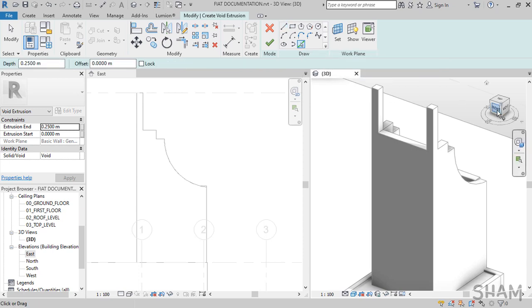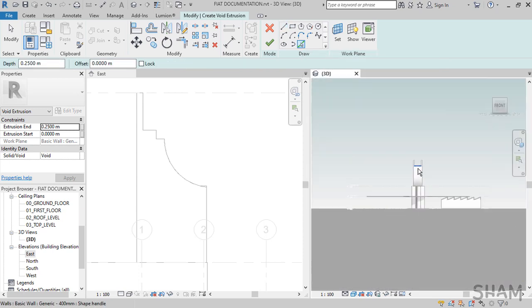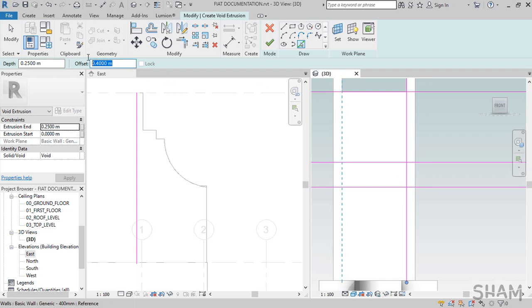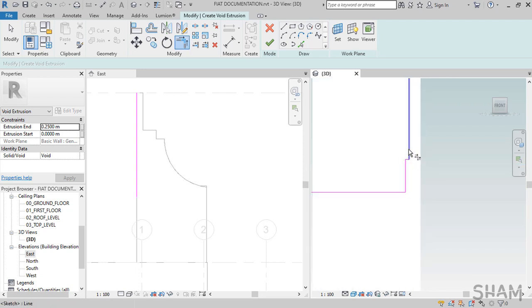The values that I'm going to use are the values that we saw in AutoCAD. The first is 4.17 from here, and the next is 1.11 meter, again 3.16 meter. Do this until you finish your reference lines. After, it's easier to clean. These lines are enough to create the shape, so let's use trim to clean the